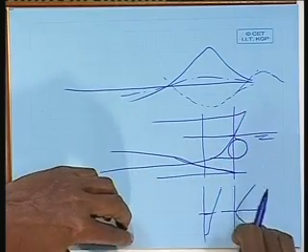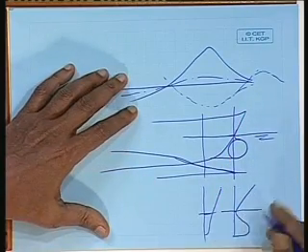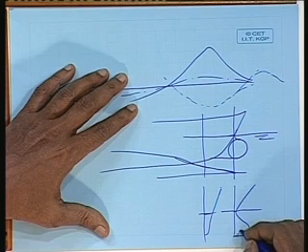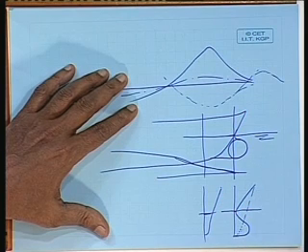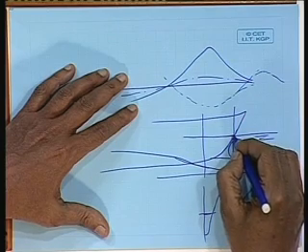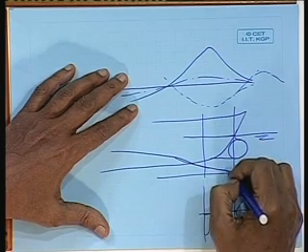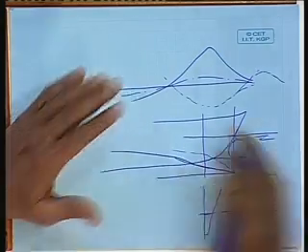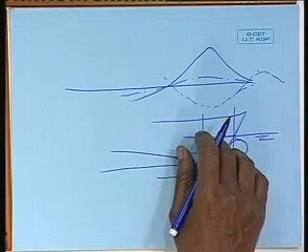If I did not have this area below, then how would my section have looked? Like that. That means I would have had a large breadth at this point. I talked about half angle of entrance. You can see by putting a bulb, I am reducing the half angle of entrance considerably. Because I am reducing this, I can also smoothen my shoulder.